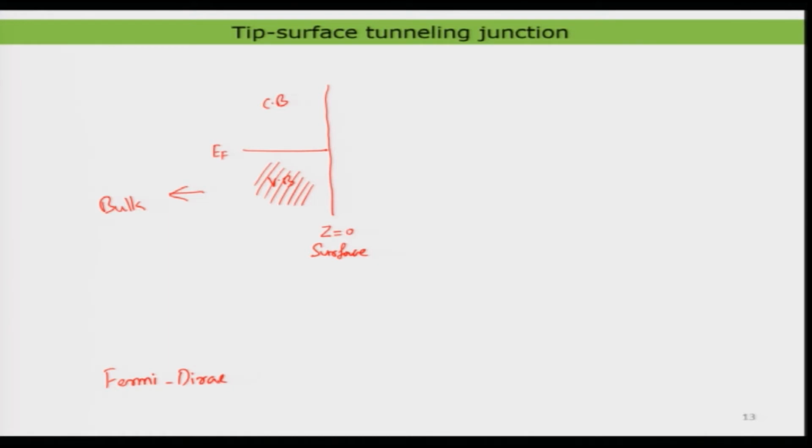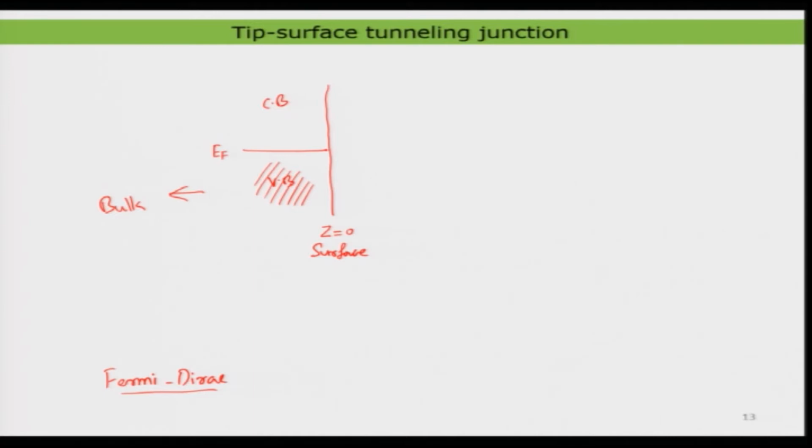That controls the population of electrons in the conduction band and valence band, and according to that you would find that at room temperature, for example, the conduction band is not completely empty. You would find a certain occupation of electrons in the conduction band, and a certain occupation of holes, which is just the opposite of electrons, in the valence band. I am not taking that into account right now. That is something you have to keep in mind for the future, but right now we are taking a situation where we assume a very low temperature, and then I have the Fermi energy defined like that.